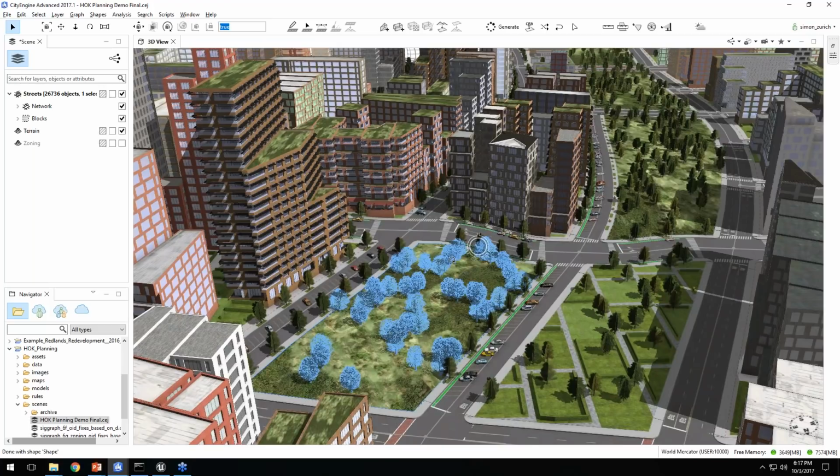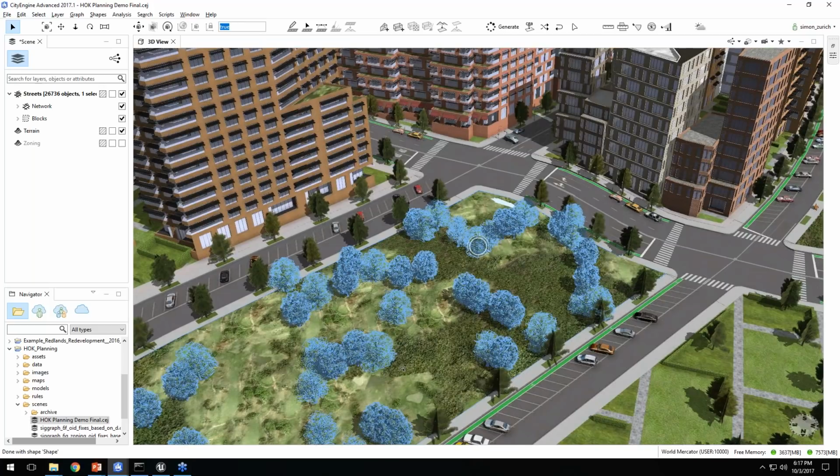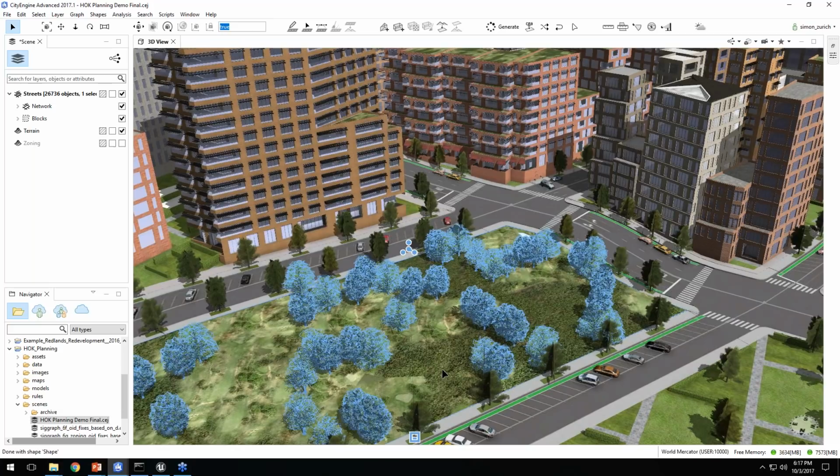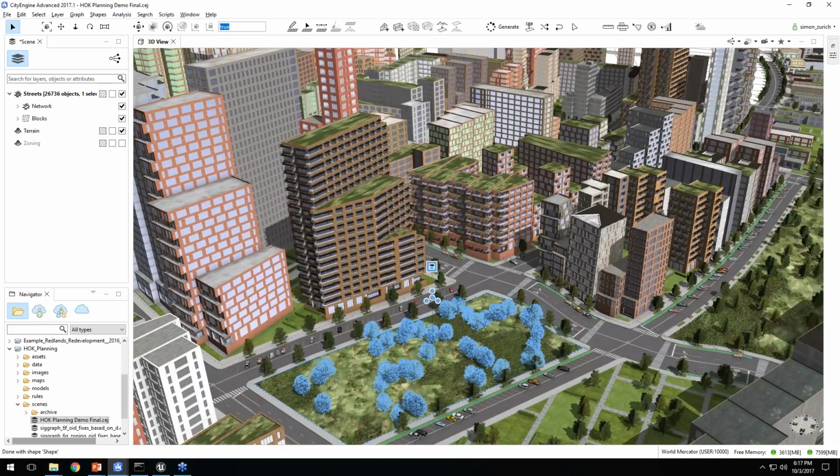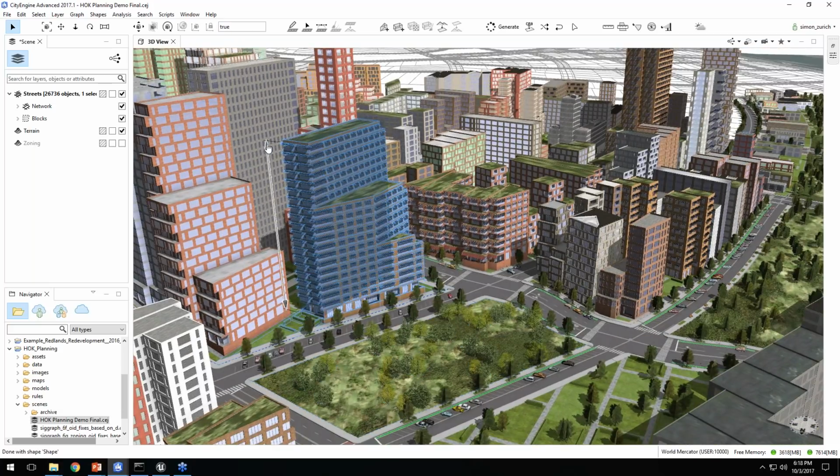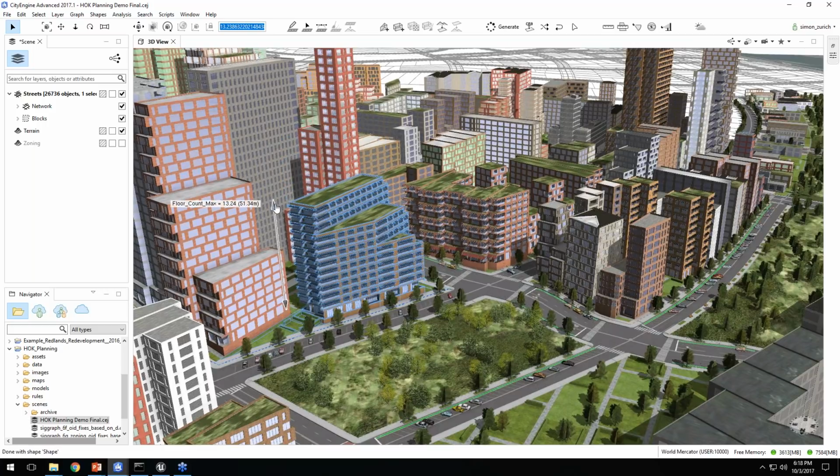And last but not least, one of the most important steps, of course, is to deal with the buildings themselves. I would just like to show you how you can edit the height of the building by grabbing this handle here, which internally, I should mention, is attached to a CGA rule attribute. You can actually specify for which of the CGA parameters you would like to see visual handles, and then you can design and set this up, and it allows you to quickly edit buildings like that.